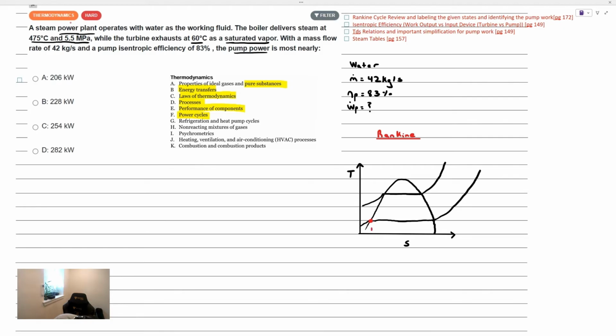And at state point 1, we essentially have a saturated liquid. You can see that we're touching the left side of the saturation dome. What we're going to do is increase the pressure of the fluid, and as we increase the pressure, we're increasing the temperature as well, to end off at state point 2, where we have a high pressure liquid. That pressure increase is occurring inside of a pump where we have to input some work in, right? A pump is a work input device. We input some work into it, and the output is an increase in pressure of that fluid.